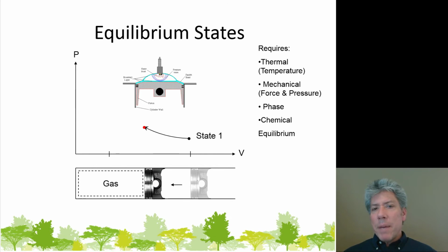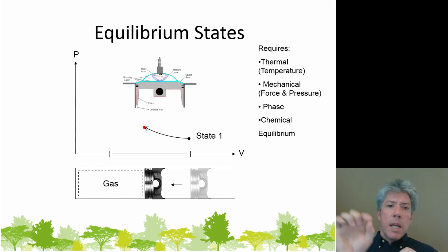Well, maybe, maybe not. Actually, high-octane fuel is fuel that is harder to burn than regular fuel. It's a molecule that's more closed on itself, so the oxygen has to attack from multiple sides more than once, so the fuel burning rate slows down, and that helps prevent detonation. So you just need to use the fuel that the manufacturer calls for in your car, and if that's high-octane fuel, fine.